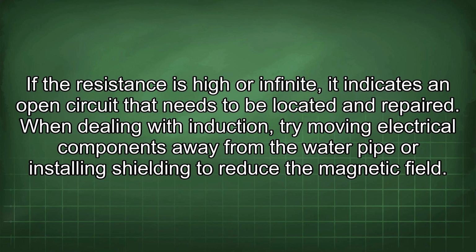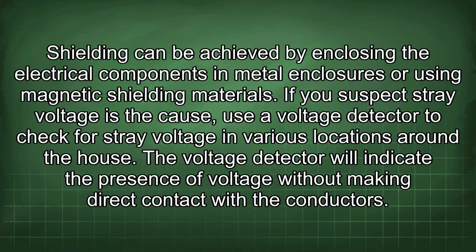and repaired. When dealing with induction, try moving electrical components away from the water pipe or installing shielding to reduce the magnetic field. Shielding can be achieved by enclosing the electrical components in metal enclosures or using magnetic shielding materials.